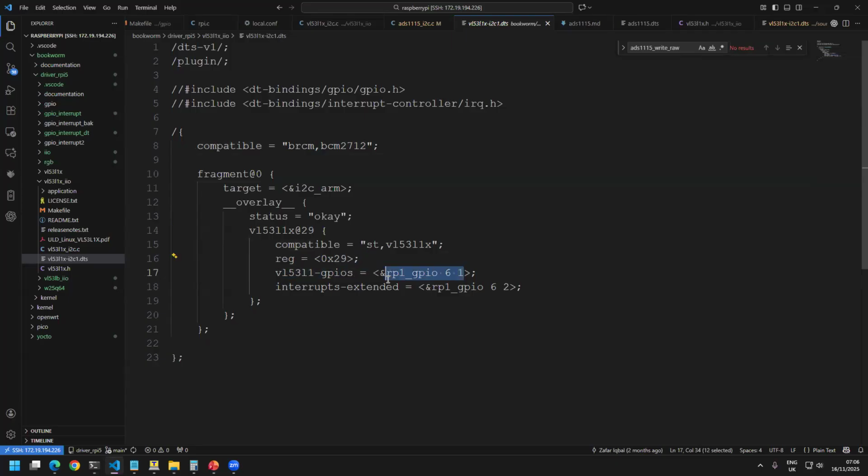The GPIO controller's name: as long as my final device's I2C address remains the same, this will be okay. But this controller's name and these compatible strings we have to change, because we have to know which particular hardware we are making use of. That's a very easy one. It can be easily found in the datasheet.